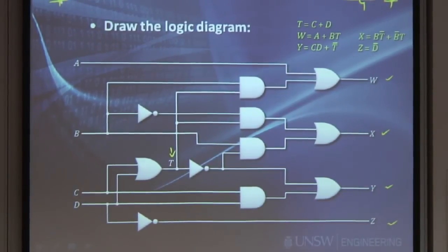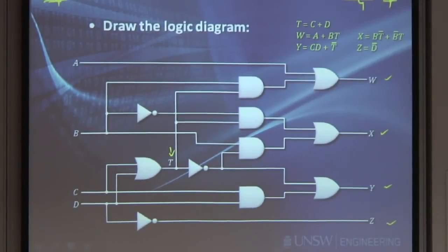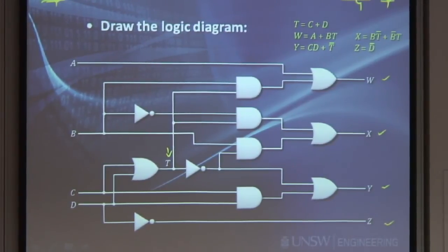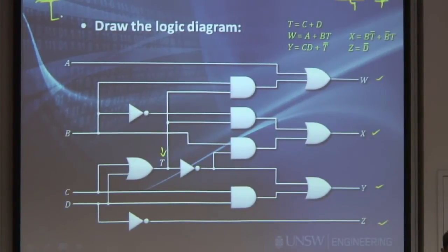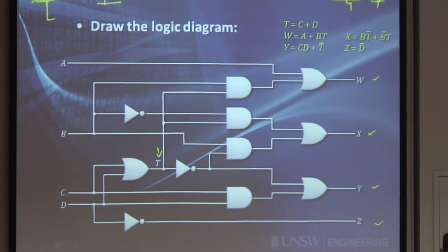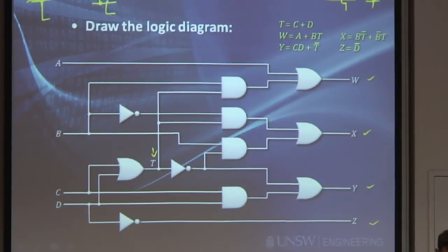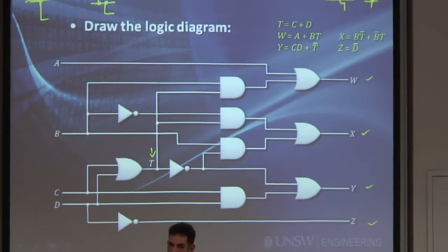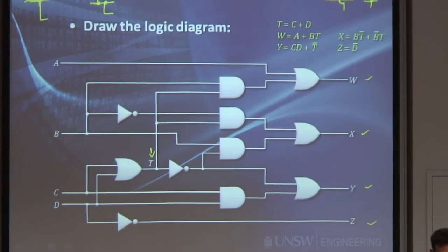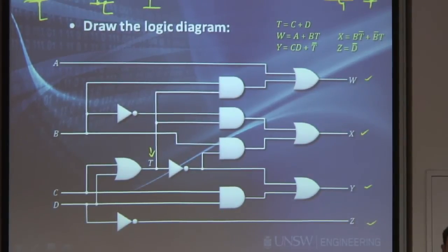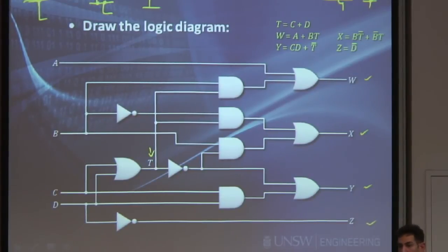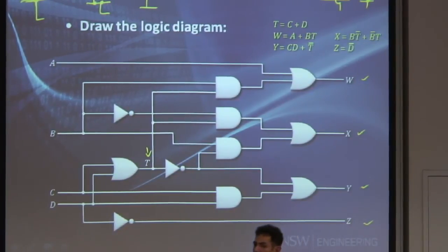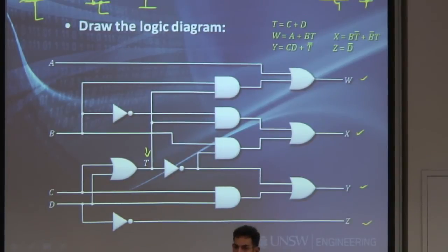If I have a line here and I need a signal to come in or out from here and another one from the bottom, I will separate them and I will draw something like this. Then there's absolutely no confusion because even if the bubbles are small or missing, you'll never have something that just looks like this if the lines are not actually connected. So that resolved this confusion, and this is the convention I will use in this course.